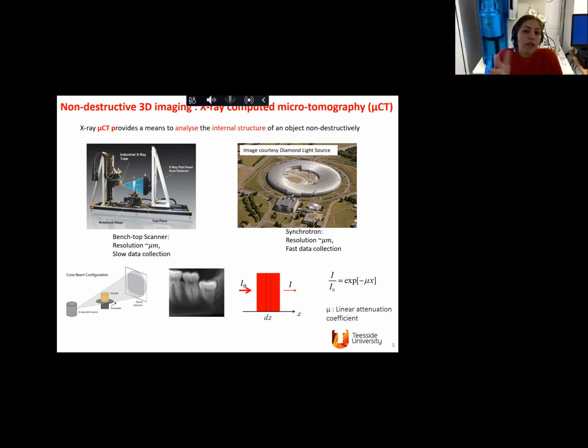So resolutions of about 1 micrometer or so are very much sufficient for what I am studying here. And you could achieve that using a desktop CT scanner easily. But of course, you need to use a small sample. So that limitation always remains, that to achieve a high resolution, you have to have a very small sample. So millimeter size to achieve micrometer resolution.